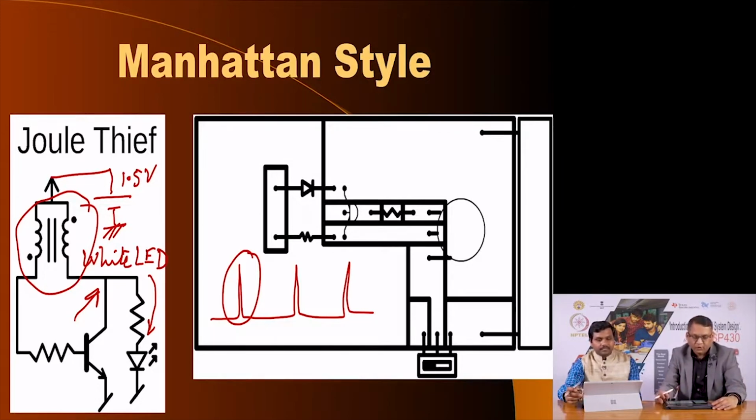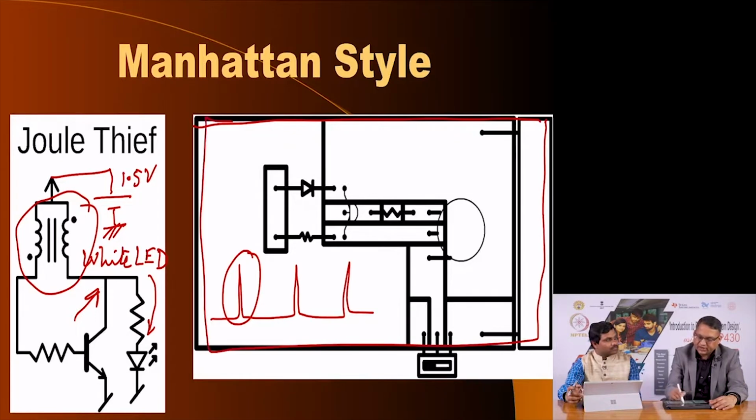Now, we wanted to show how such a circuit can be fabricated using this Manhattan style circuit board. So, for that we first created a layout, meaning given this circuit, how would our components be arranged. Here you see this dimension would be our printed circuit board.